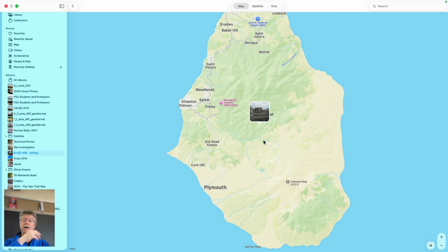And so tilt meters are developed actually by the company that was developed by Chris Wright, who's now the Secretary of Energy in the current administration. He built a whole company out of this, Liberty something, who developed this technique to be able to put tilt meters in the ground. So you drill a hole maybe 3 feet deep. You'd put this long, slim, 4-inch diameter tube in it in the bottom. This thing would have a little, like a spirit level in it, which had mercury in it, and it could predict or measure electronically the tilt of this meter in the borehole.